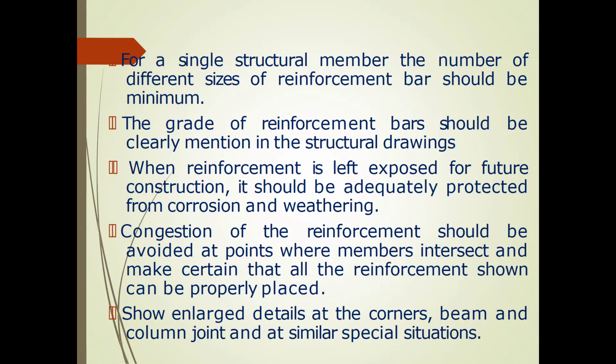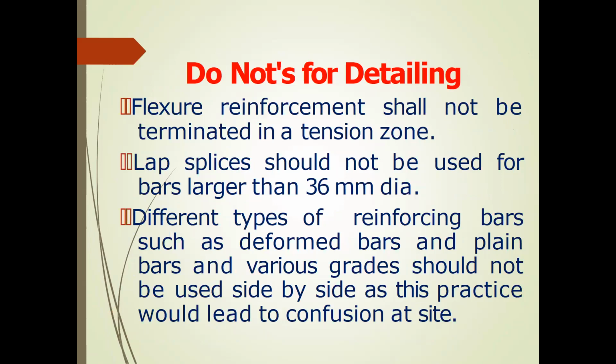Congestion of reinforcement should be avoided at points where you can provide a pin, etc. So enlarged details, and our structural consultant is supposed to show the enlarged details of the corners, beam and column joints and special locations.